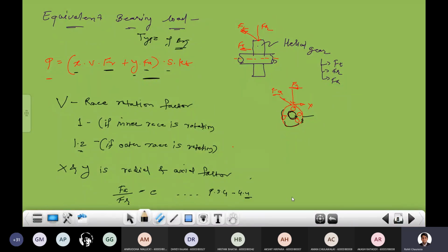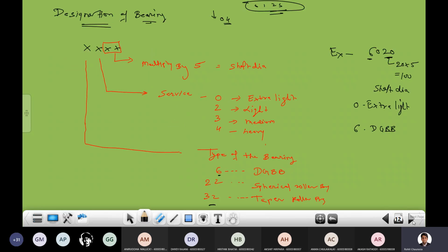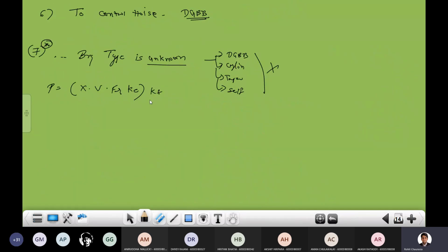You can proceed. Suppose you don't know the type of the bearing, question में सिर्फ load requirement दिया है, we need to calculate which bearing is suitable. At that time the type as well as other parameters like X and Y we need to calculate. In that case, मेरे को जब तक type of bearing पता नहीं है, I am not able to do the equivalent. So in that case, I can use this one. In this one, I can take X equal to 1 because this is the equivalent formula without this. So you can say here we are trying to find out the one lump sum equivalent.